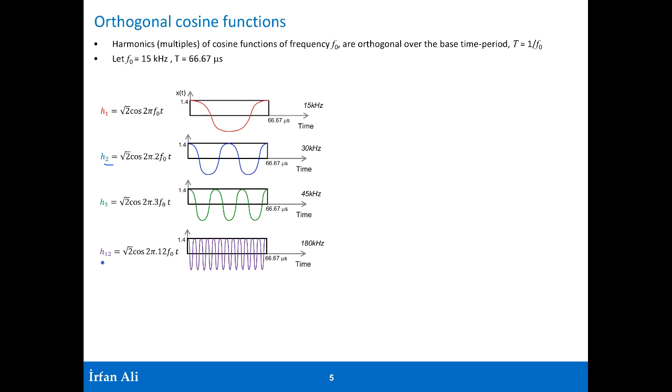Like this, you have the 12th harmonic. In order to send 12 bits of information using these 12 harmonics, each bit you either multiply by 1 or -1, depending on whether you want to send a 1 or a 0, and then you sum up these signals, and what you get will be the composite signal G. Over here we do it slightly differently, just to illustrate that you can find out the energy in the H1 component.